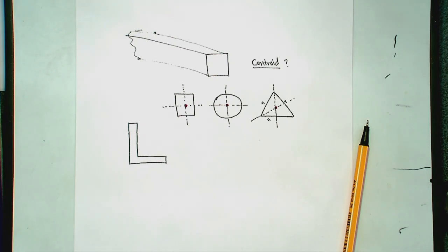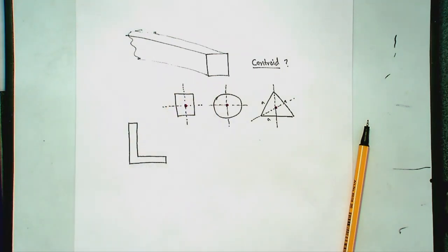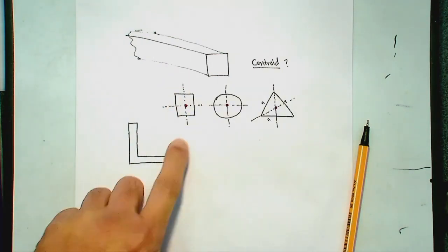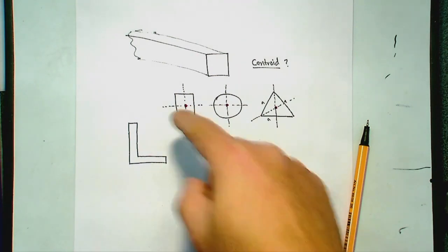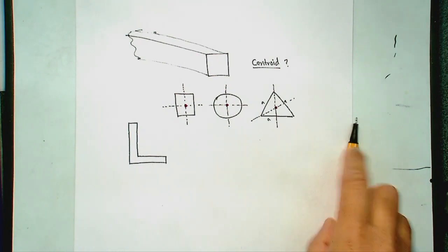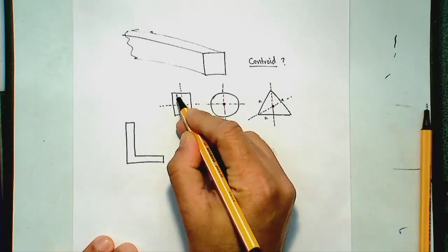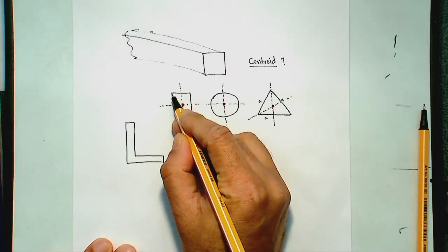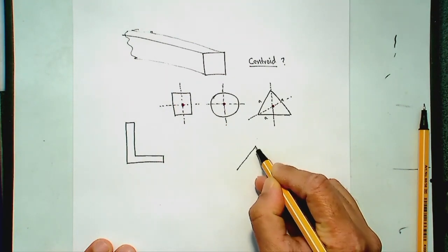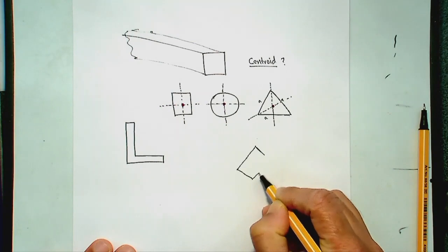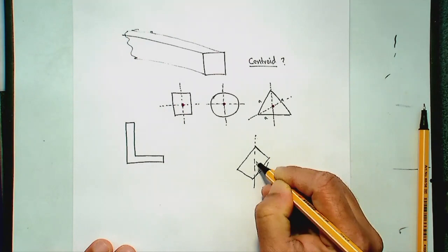So one way you can find the centroid is you can cut out a shape, say a rectangle, and then you hang that piece with a piece of thread, for example, and of course due to the weight it will hang. If you take this rectangle and put a string attached to the corner, then it will probably hang vertically down, probably that way. So its centroid would be along that line somewhere.